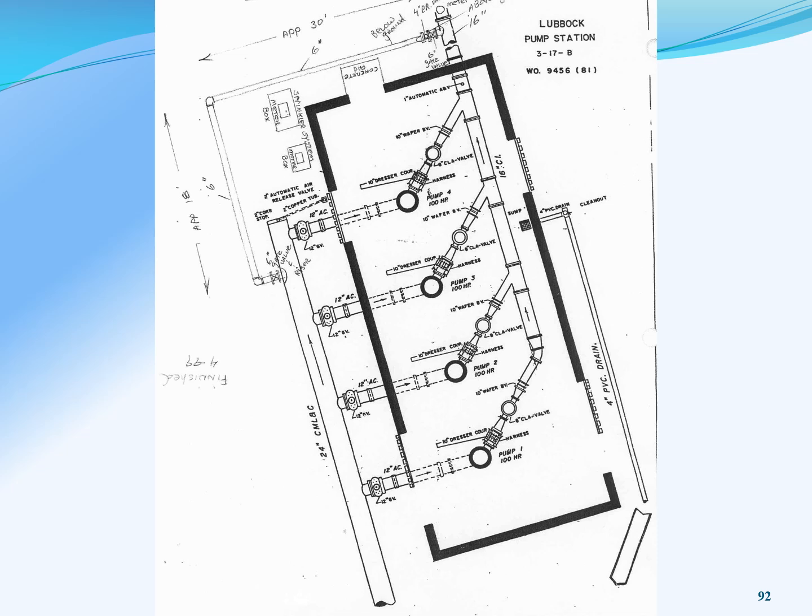You've got water that is coming into the pump station from this 24-inch CMLC pipe going through your pumps and then being discharged out into a 16-inch concrete line pipe. And then, like I said, here's that recirc, so if it overpressurizes, this valve here will open up and then discharge back into the low suction side to prevent overpressurization. And so yeah, this is just a basic as-built of a pump station.